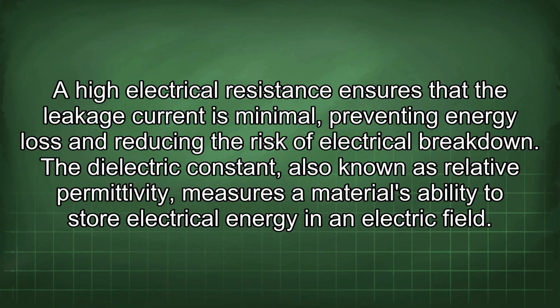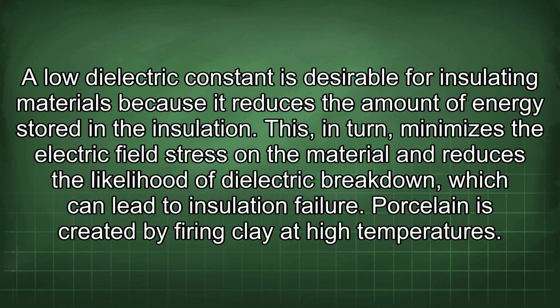The dielectric constant, also known as relative permittivity, measures a material's ability to store electrical energy in an electric field. A low dielectric constant is desirable for insulating materials because it reduces the amount of energy stored in the insulation. This, in turn, minimizes the electric field stress in the material and reduces the likelihood of dielectric breakdown, which can lead to insulation failure.